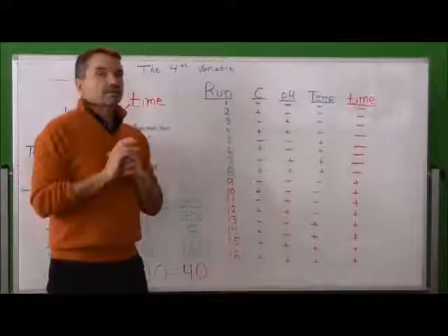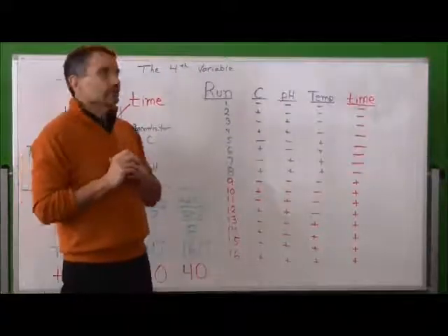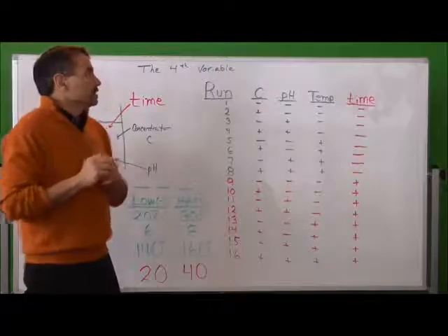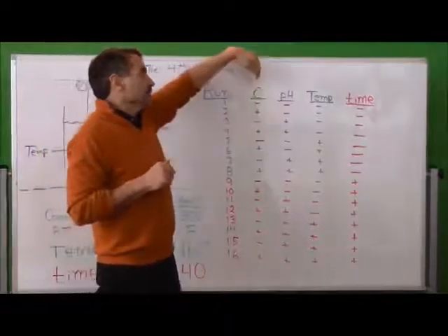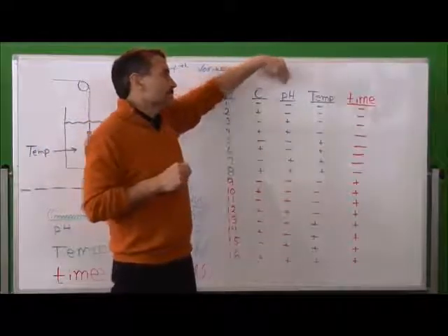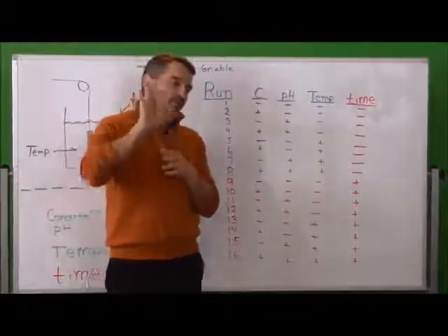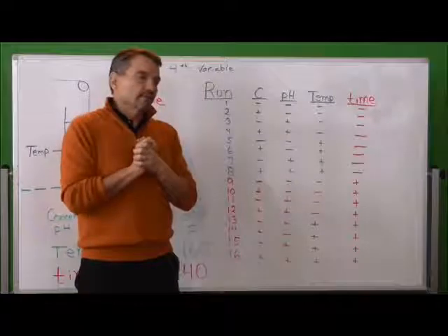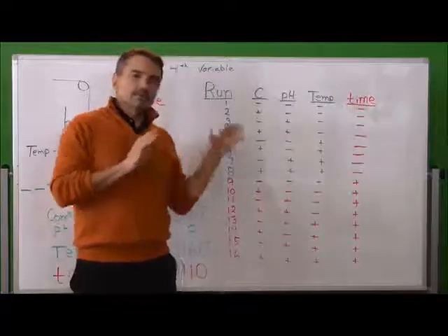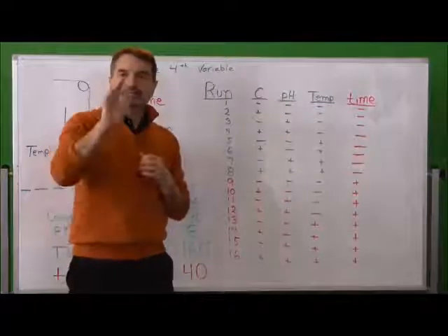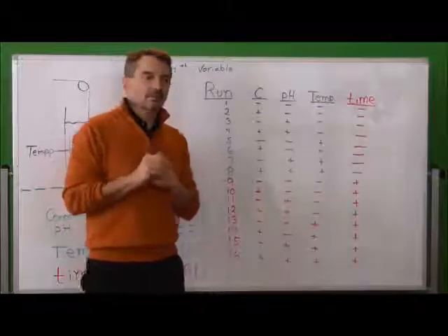And doing it as a full factorial has one big benefit: if all four of the concentration, the pH, the temperature, and the time together are needed to be at a certain level to eliminate the defect, this design and this DOE will actually find that four-level combination.